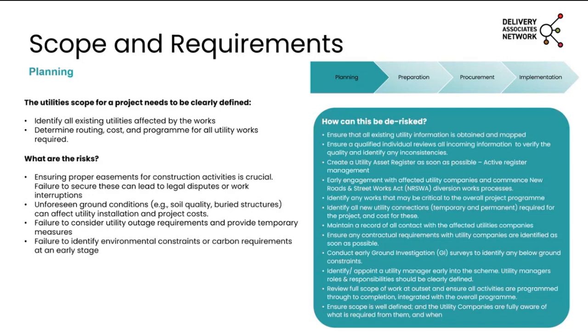There is a significant amount of risk around all utility works. As I said, determining what utilities you've got in the area is critical to this, but there is always a risk that you won't. Records are not particularly good. They're not always kept up to date, so you will likely encounter unforeseen problems.